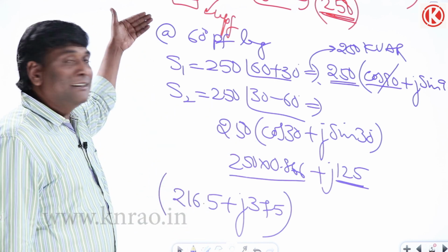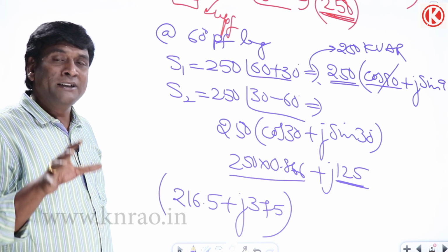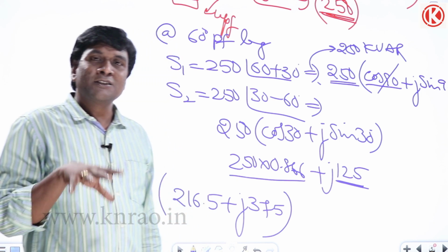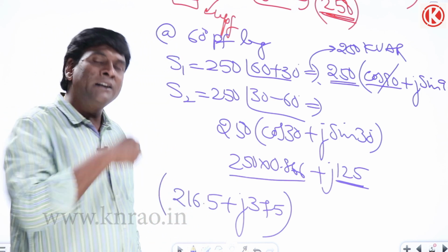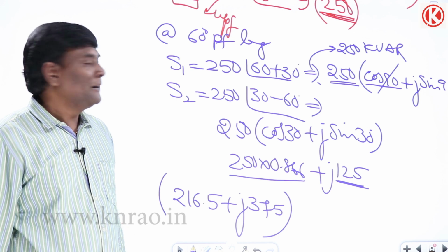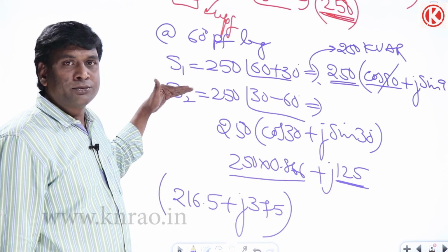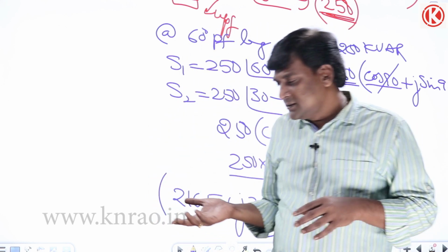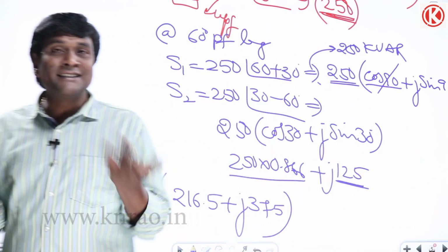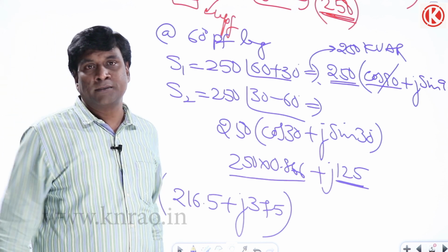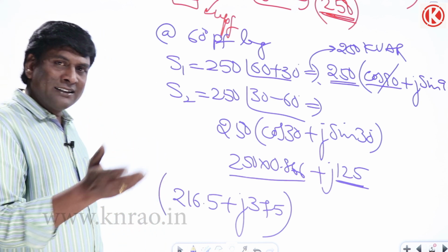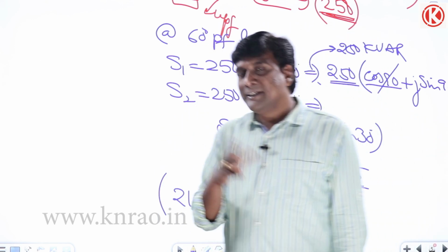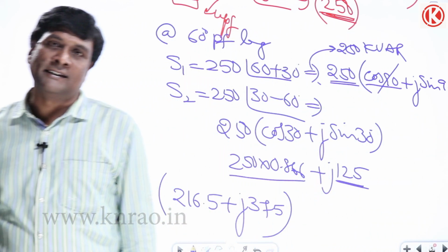But at 30 degrees, whatever reactive power is supplied by each transformer goes directly to the output, and the active power delivered combines at the output. At 60 degrees also, it is the same. The condition where one transformer supplies and another absorbs reactive power was considered only at unity power factor. That is decided by whether the power factor angle is more or less than 30 degrees.